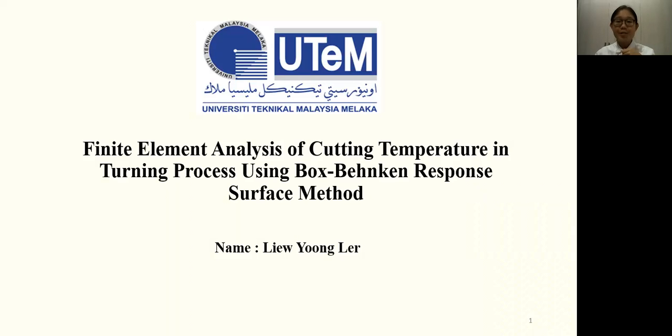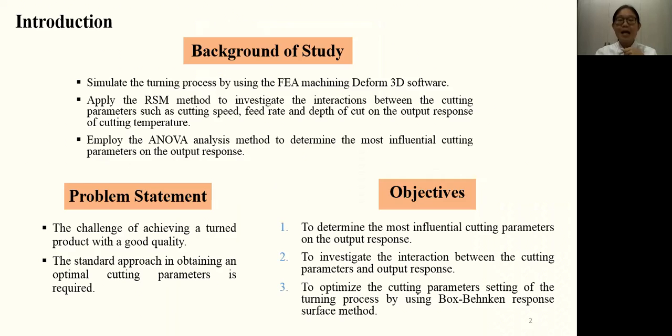My name is Liew Yoong Ler, and today I'm going to present my study with the title of Finite Element Analysis of Cutting Temperature in Turning Process using Box-Behnken Response Surface Method. This study is focused on the simulation of the turning process by using the FEA DEFORM 3D software. Furthermore, the interaction between the cutting parameters and the output response are investigated by using the RSM method. Then the ANOVA analysis method is employed to determine the most influential cutting parameters on the output response.